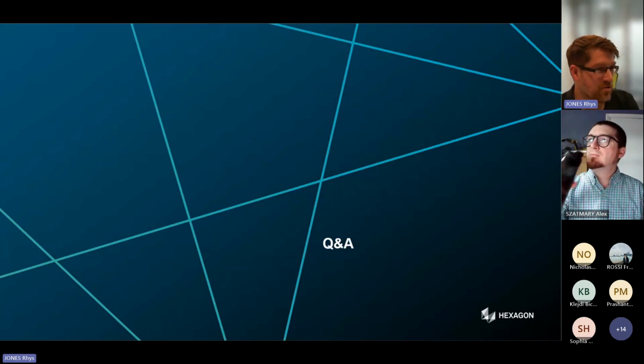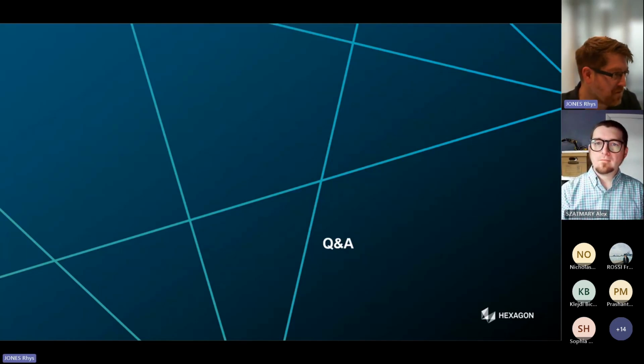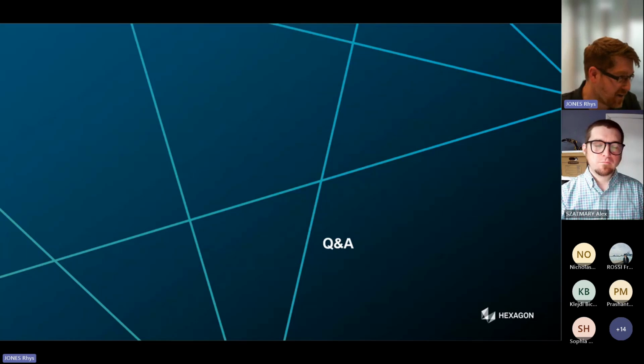So with a bit of matrix wizardry, if you wanted to go into detail into this, the process technically is called Guyan reduction. It's the process that you go through, and essentially it reduces that matrix from 400,000 elements down to the bits that you're interested in. So it's basically creating a stiffness coupling between the points of interest.